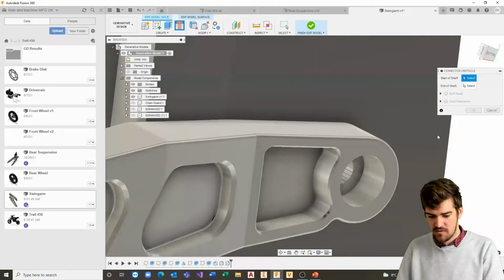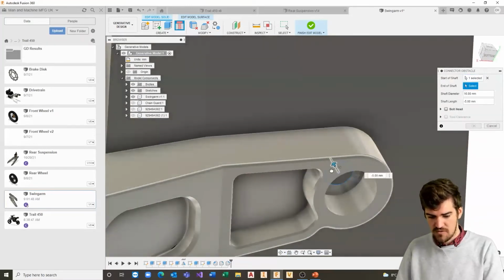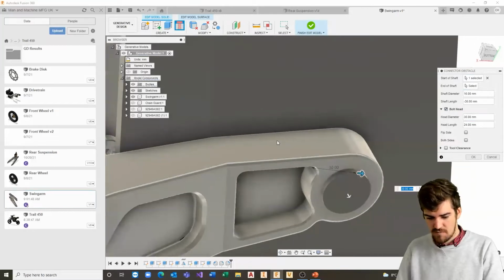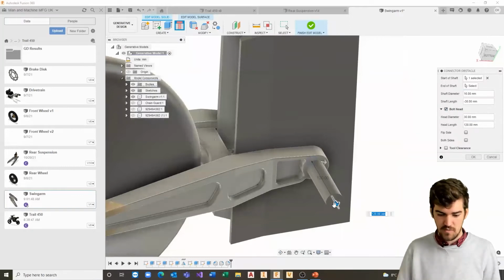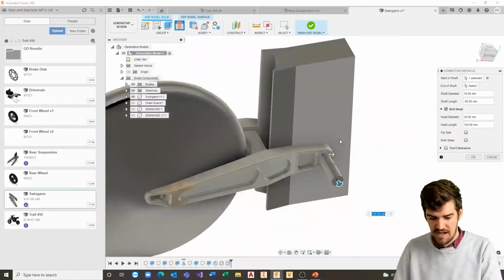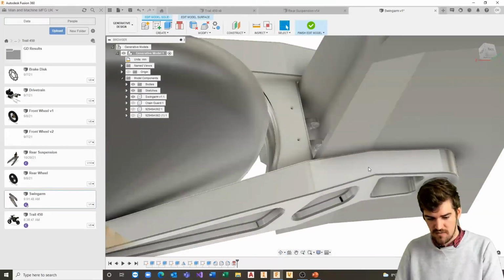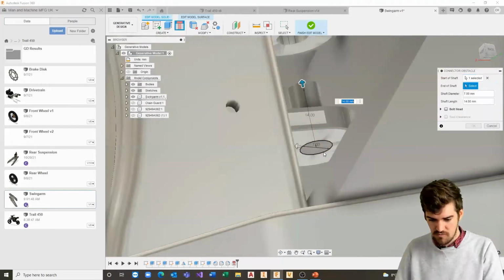And you can see we start off with the shaft of the object itself. We can extrude that all the way through, and then we can add a bolt head as well to the opposite side. We can adjust the thickness of that as well. And then just to compensate for any extra space that might be needed to put the bolt in, we're just going to extend that out a bit on that one there. We're going to do the same on the inside over here as well. Again, just to make sure that we've got room for those. That extension should be fine.